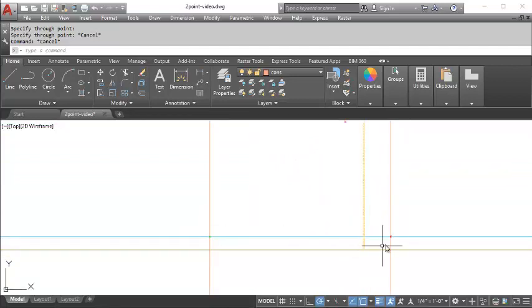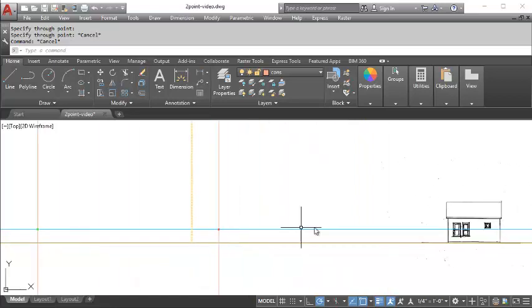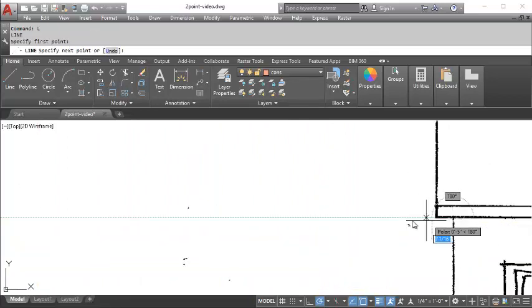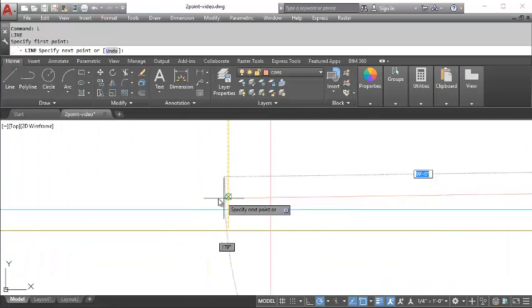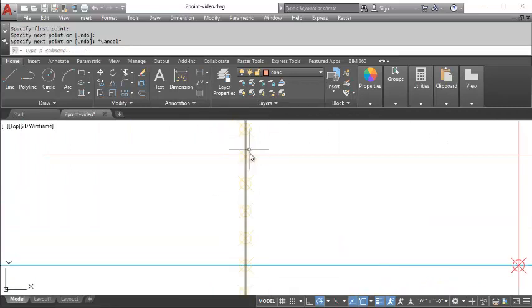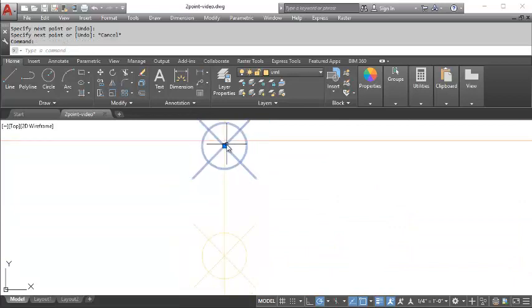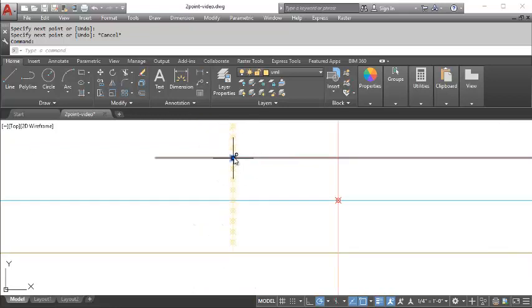We also need to define the floor line and the ceiling line of the walls. So I'm going to do that by transferring my height from the height of the wall. I'm eyeballing this from my sketch. Bring that over to my vertical measuring line, and it's just about hitting this mark here. So you can either use this point that you've projected off of your sketch, or if you would like to make it a nice even number, you can go from there if it's that close. So I'm going to use that.